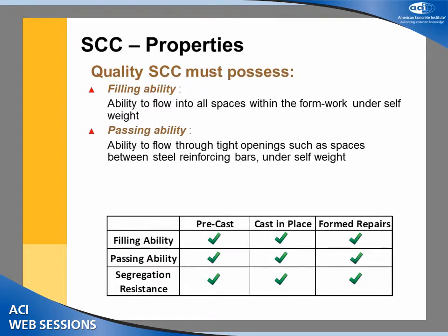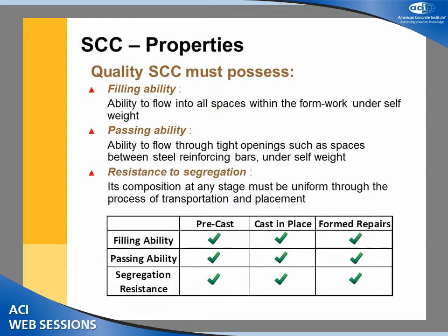As far as filling ability goes, you have to make sure that the material has the ability to flow into spaces within the formwork under self-weight. Passing ability, we have to make sure that the base material is able to pass through reinforcement, congested reinforcement. And the last thing is the segregation resistance. No matter how fluid the mix is, it has to be segregation free, so it's not going to separate out.